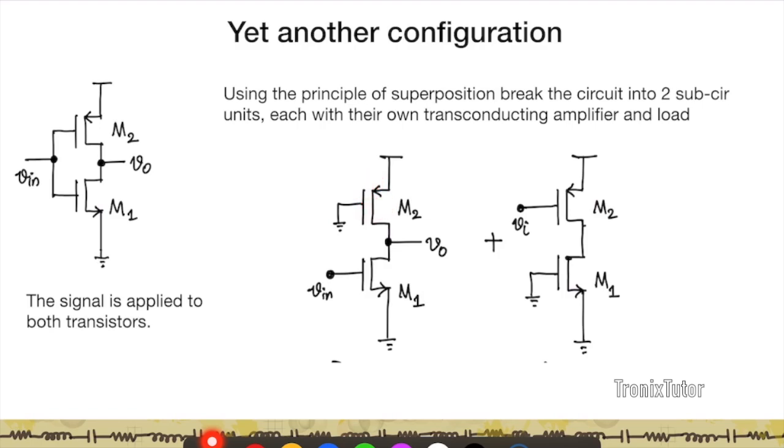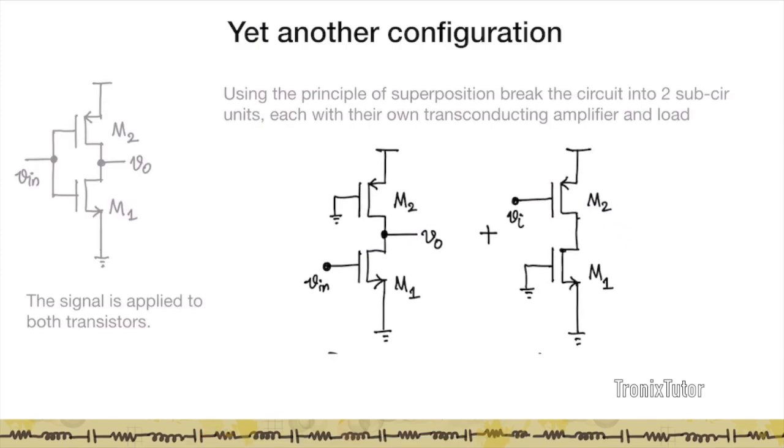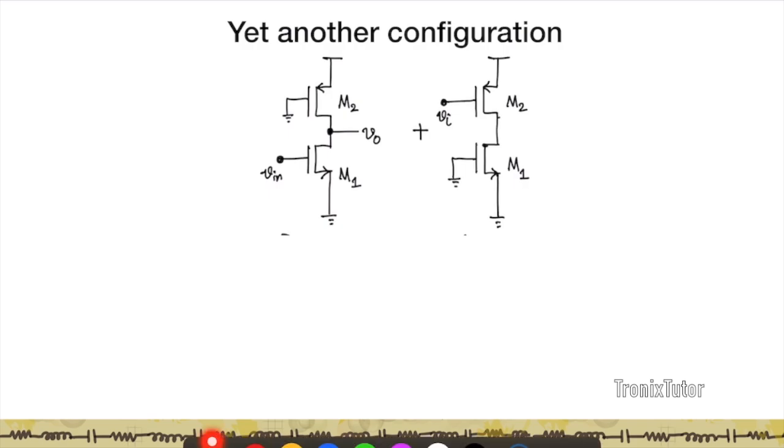And I think of the second subcircuit as one where the signal is given to M2 and the input to M1 is grounded. Now these two individual circuits are easy to analyze because I have input going into only one transistor. And so I can estimate the voltage gain of this circuit, estimate the voltage gain of this circuit, and the sum of these two is going to be the voltage gain of the overall circuit. So now let's estimate the gains of the two circuits.